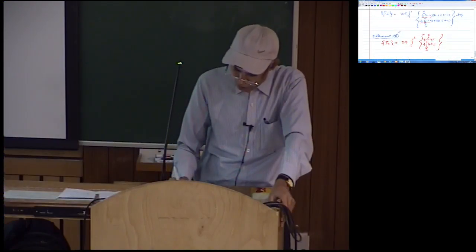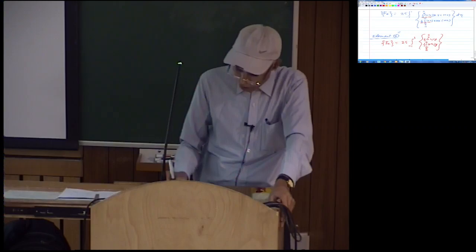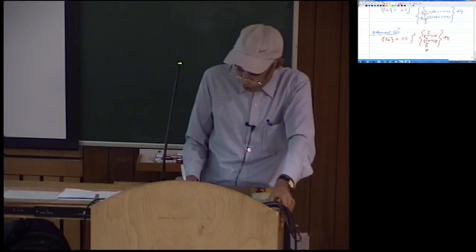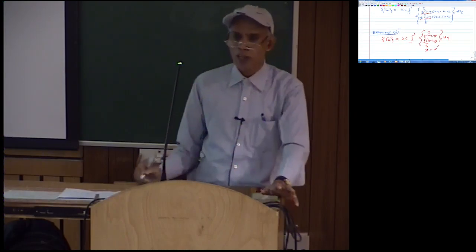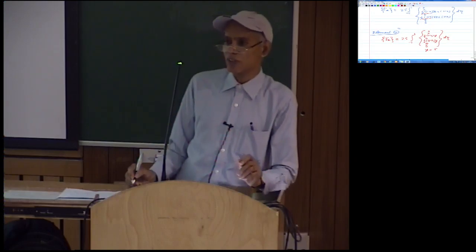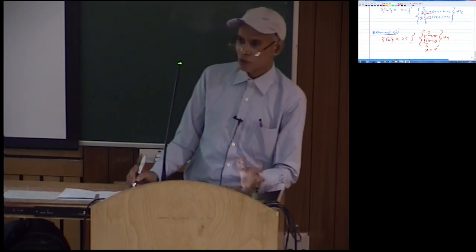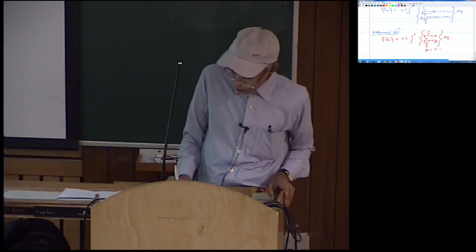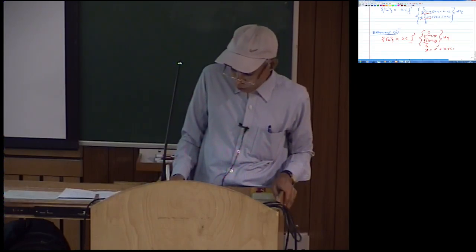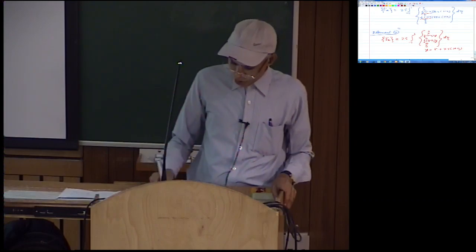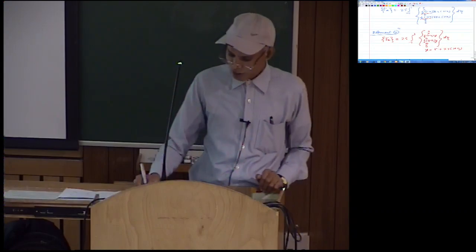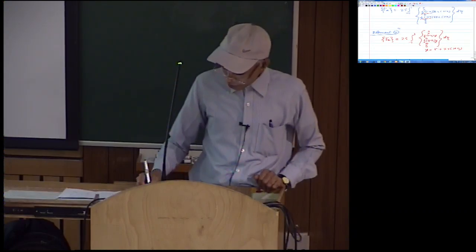So here you will have in addition your y, and of course this is d eta, the same as what we have there, and y is going to be phi plus, you actually again n1 y1 plus n2 y2 plus n3 y3 plus n4 y4. Put the appropriate values of y1 y2 y3 y4, you will get y as phi plus 2.5 into (1 plus eta). So you just have to put this value here, do the integration with respect to eta, you get the load vector for the second element.